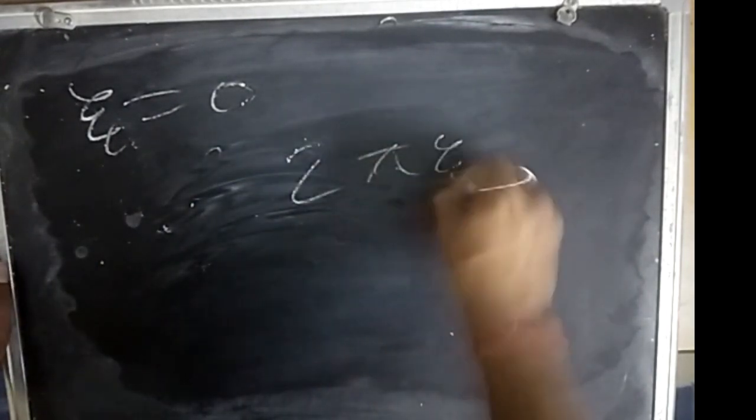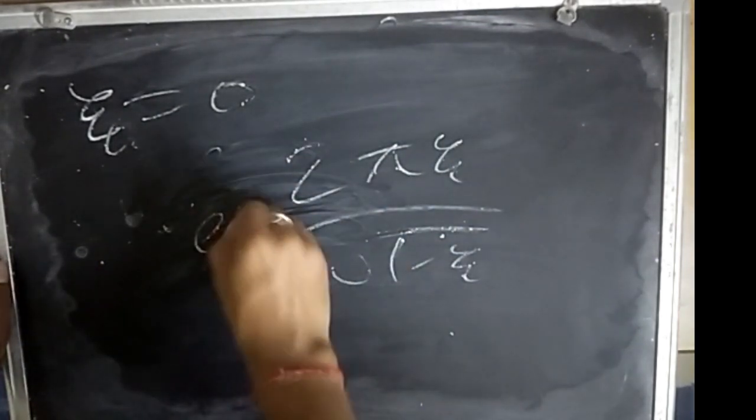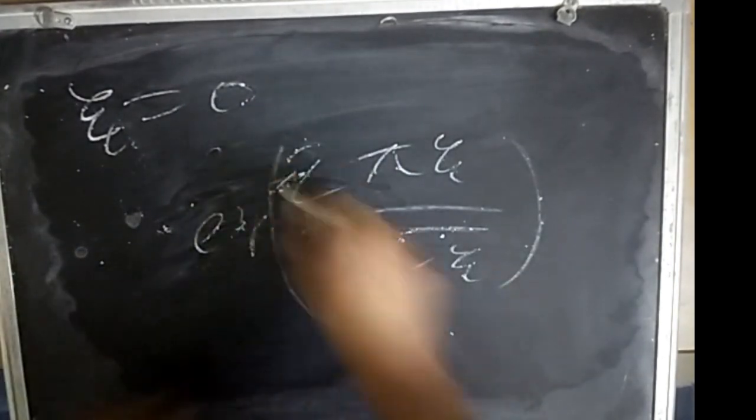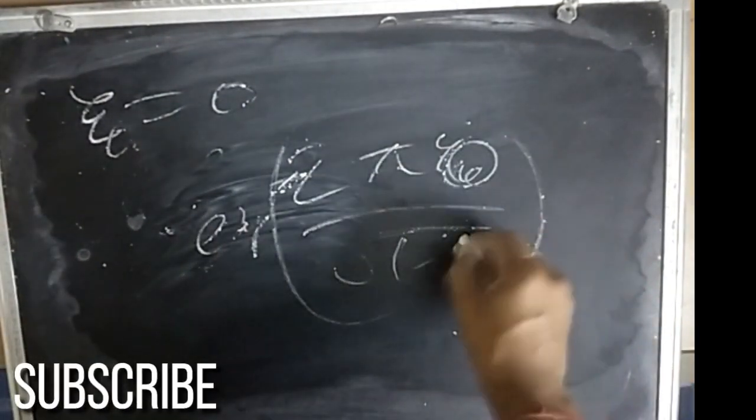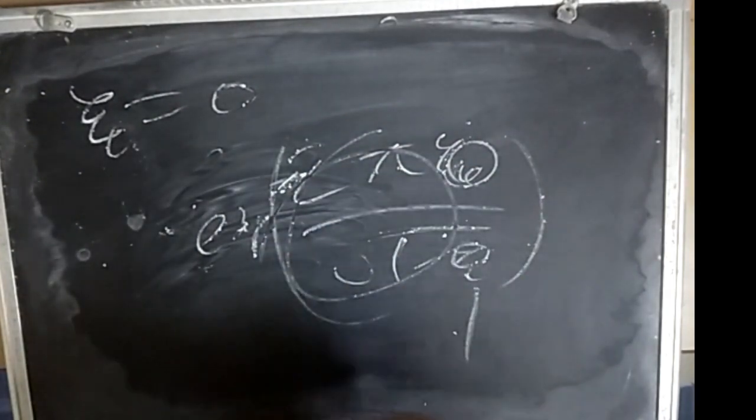in this case. And you can even put this like e raised to power minus 2 pi zeta upon root of 1 minus zeta squared. This is exponential. There's a minus sign also. So zeta is 0, so this is 0, this is 0. So this is e raised to power 0, which is 1. Okay, so decay ratio is 1. When this happens, the same peak would be there, so it is oscillatory.